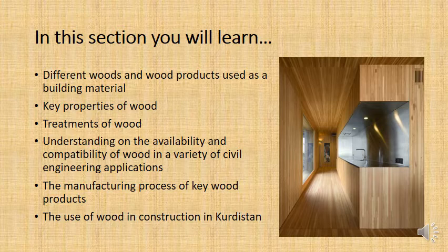And basically we also talked a little bit about how variability in moisture content can wear out the wood because it is always swelling and shrinking. We also talked about how sometimes we want to have a high moisture content, because that means we can bend the wood into the shape we want, and then lower the moisture content, and because it's plastic deformation it will stay in the new shape.